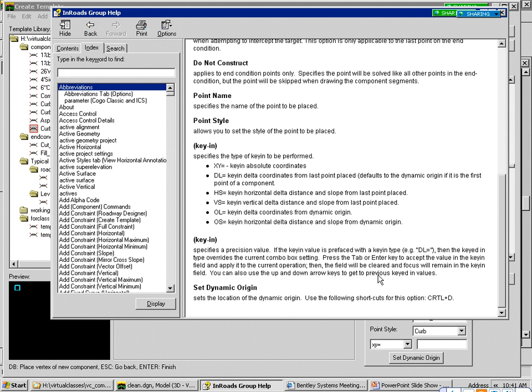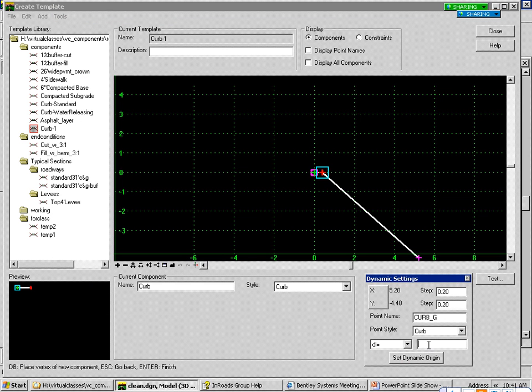So I'm going to use a DL. So I'll say DL, and I'll say 1 inch. If I go 1 inch, comma, down minus 0.5. Okay, minus, help if I key it in right. 0.5, and I hit enter. When I hit the enter, it places the element, and it converted that 1 inch to the same units. So that was pretty neat. I wanted you to see that as it went.